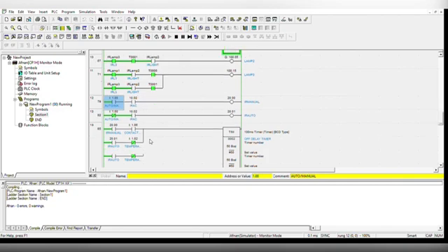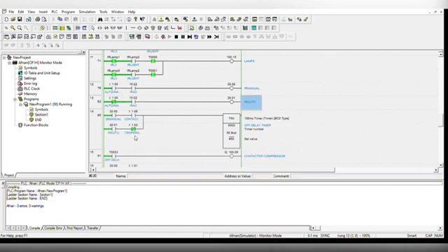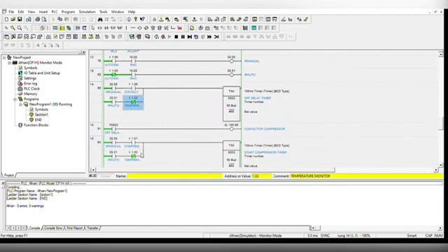Next is the air conditioner, where we have auto and manual, and this is the button for our air conditioner, which is on manual, and when the auto manual is normally closed, the air conditioner will become auto. For the manual button, we have the contactor manual, which connects with the timer, and we also have the temperature monitor.